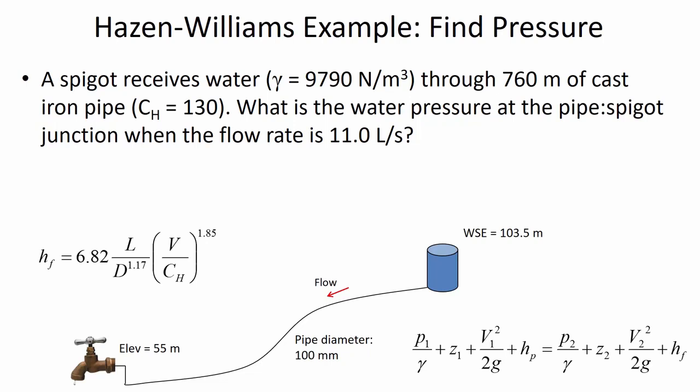Some of the energy was being left in reserve so that there would be pressure in the pipe. If you exchange that energy, instead of keeping some of it in reserve to pressurize the pipe, and you spend it all on overcoming pipe friction, then you can move the water at a faster flow rate. Remember that this was potential energy. The water in a tank up on a hill is potential energy, and we're transforming it into movement, which causes pipe friction, and then pressure.